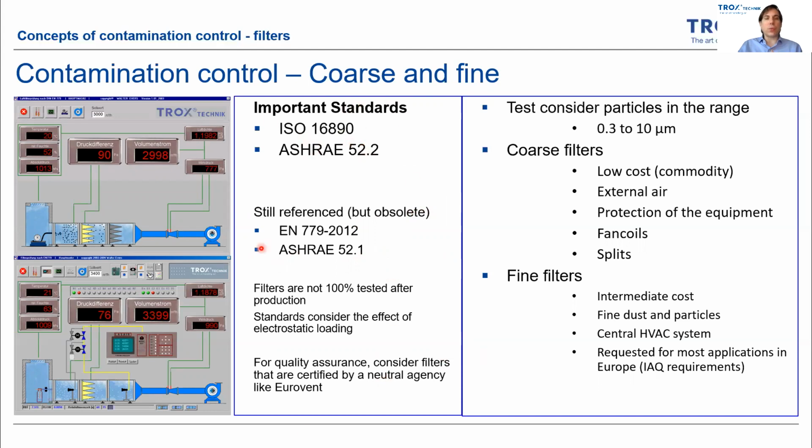It's important to consider that for these filters, we do not make tests of each filter at the end of the manufacturing. The tests that we do with these filters are destructive tests. So after the test, the filter is not usable. And that's the reason we develop the filter, we do the testing, we get the classification, and then at the big companies, we do tests for quality control, to know that the media is still what the supplier says.